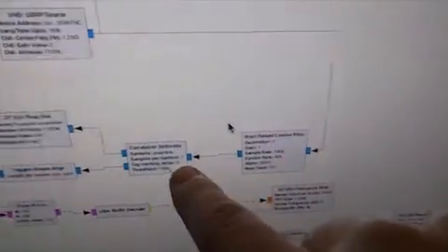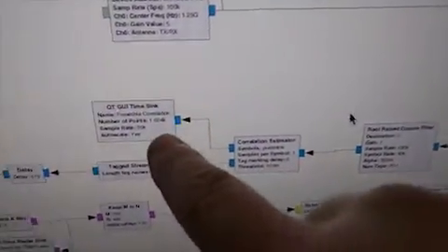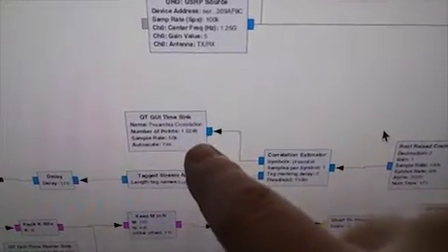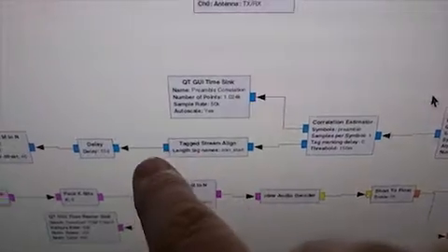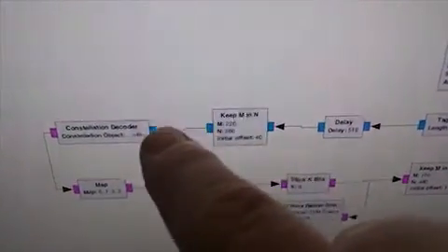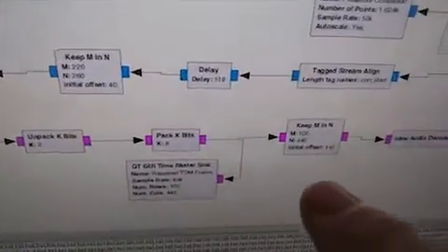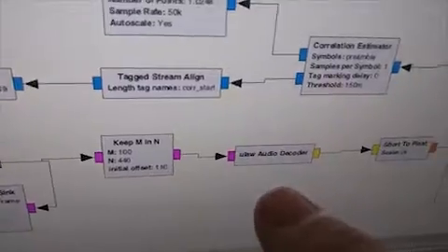So we get a receiver here at 1.25 gigahertz feeding samples into the receive filter. It goes into a correlator looking for the preambles, and that's where the visualization of correlations comes from on screen. And then it decodes it all through all this stuff. This pulls out the right bits you want, decodes the constellation, maps it. I don't know exactly what all this stuff does, but it essentially just receives it.